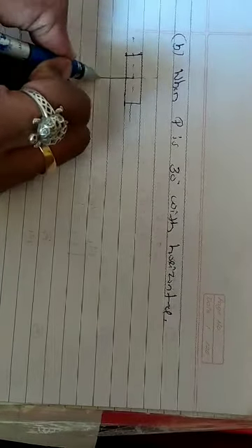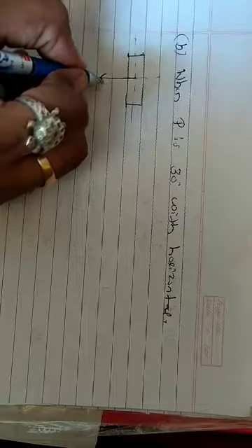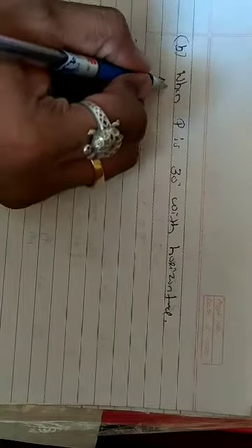So similarly here, first the weight of body A, that is WA, acting vertically downwards. Normal reaction will be acting vertically upwards. We'll call this N1. There's a tension force T acting in this direction, that means the body is moving in this direction. Frictional force acts in the opposite direction. We'll call this F1. The first part is over.